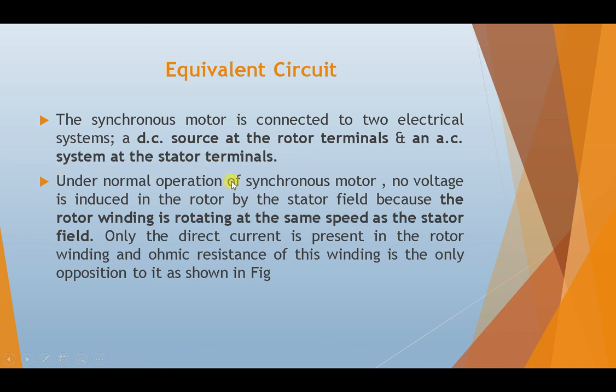When operating normally, no voltage is induced in the rotor by the stator field because the rotor winding is rotating at the same speed as the stator field. Meaning at synchronous speed, when the motor is rotating, there is no voltage induced in the rotor.